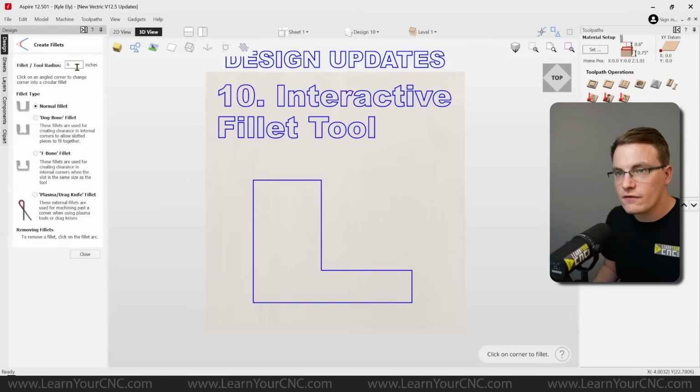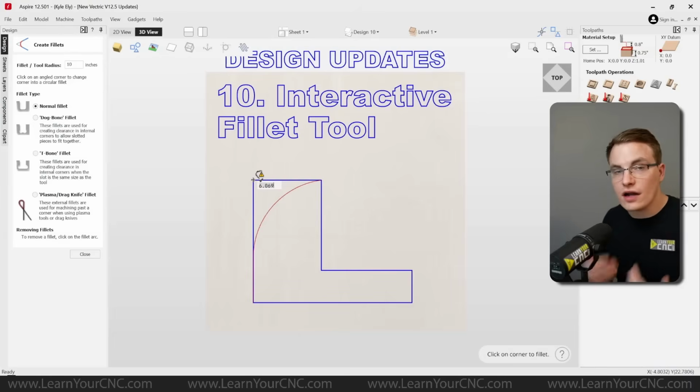And another thing, if you try to make a really large fillet, let's say 10 inches, and I hover over this spot where it's not going to fit all the way, it will actually reduce the fillet to where it will work, but it gives you an alert letting you know that it's going to do that. So that way you don't have to keep guessing on the number for the radius that's going to fit there. It will actually tell you the exact radius that's going to fit and it will automatically reduce it. It does give you a little warning on your icon showing you that it is reduced. So when you click on it, it will still work without having to type in a bunch of numbers to guess what will work.